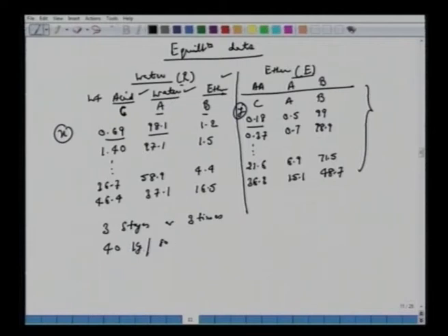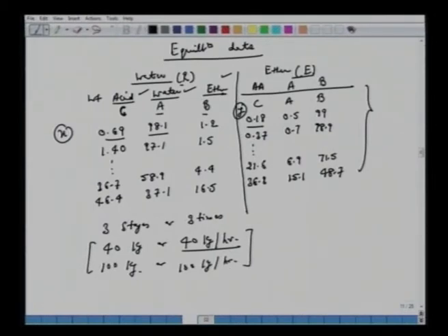All right. So now all we do, we first draw this equilibrium diagram, but notice here that our feed was given as 30%, weight by weight, and look at the y versus x diagram. The extract composition of the solute is smaller than the solute concentration in the raffinate. That means we can stop, or we can plot only till here where the feed composition is 30%.